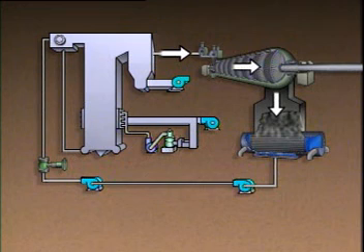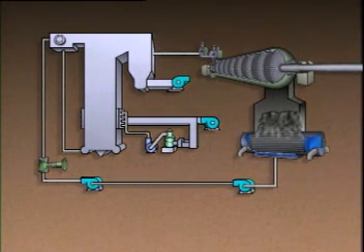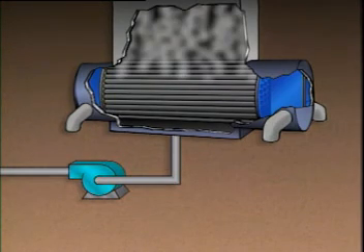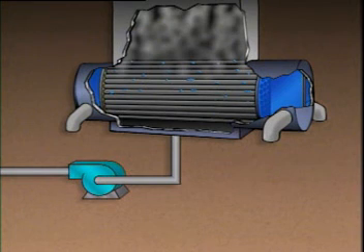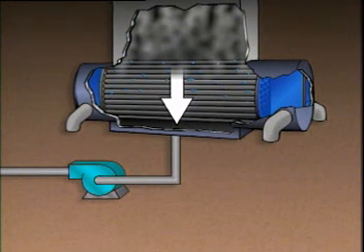As the steam gives up its energy in the turbine and is converted into water in the condenser, the pressure drops dramatically. When steam first enters the condenser, it fills the available space. But as the steam condenses, taking up less and less space, a vacuum or negative pressure is created in the condenser. This negative pressure tends to draw more steam through the turbine and into the condenser.